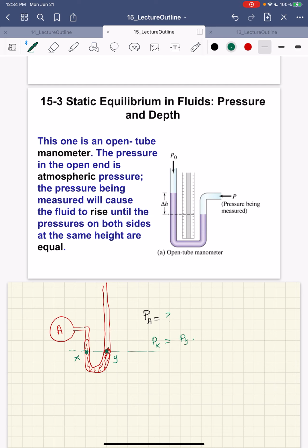Then the difference in pressure equals 85 millimeters mercury. I like to convert that into pascals. I did not calculate my number because I know that the difference in pressure should equal rho times g times h. My objective is to cancel some of the quantities, so I cancel 9.8 from both sides. I'm using mercury here, so it is 13.6, the density of mercury.